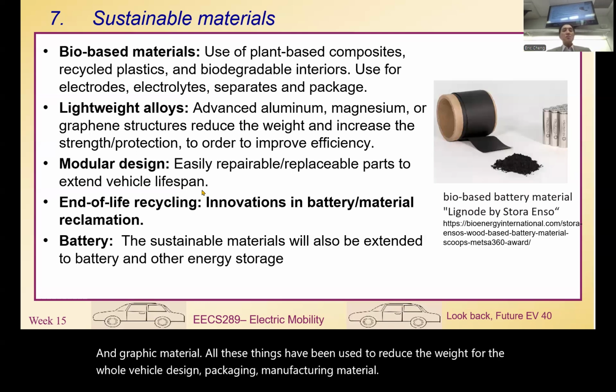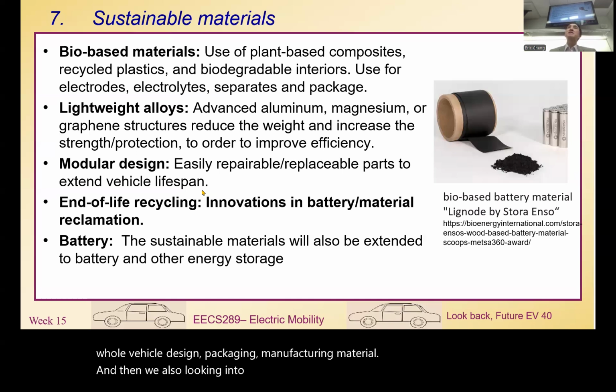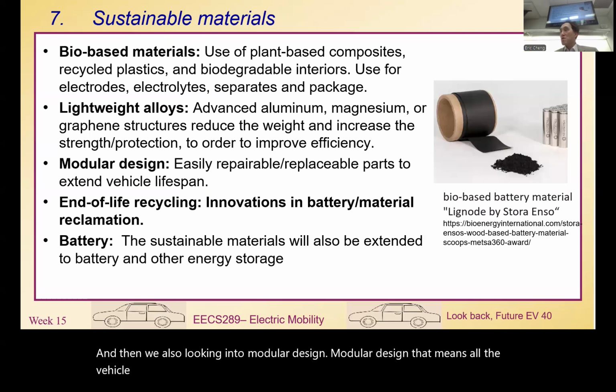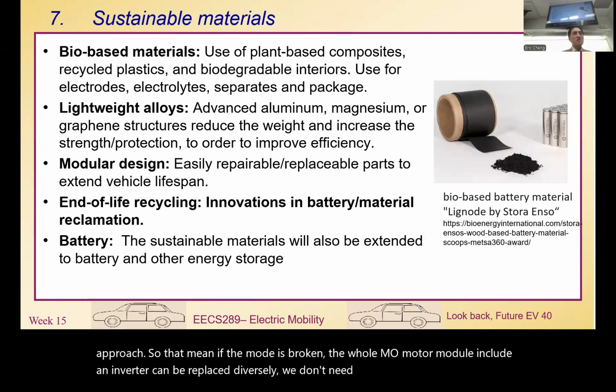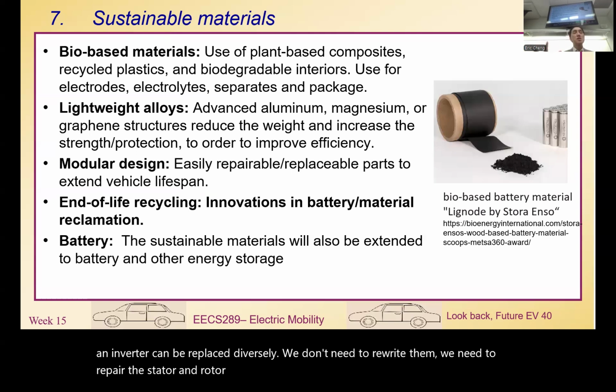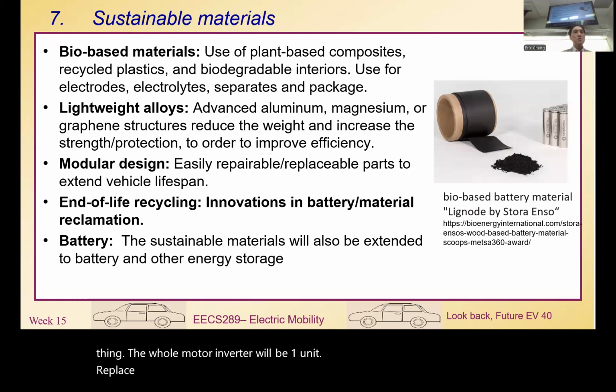And then we're also looking into modular design. Modular design means the vehicle is not constructed from individual components; it's constructed by a modular approach. So if the motor is broken, the whole motor module, including the inverter, can be replaced directly. We don't need to rewire them. We don't need to repair the stator and rotor and inverter and IGBT. We don't need to do the whole thing. The whole motor and inverter will be one unit, and we just replace it. The charger is one unit.